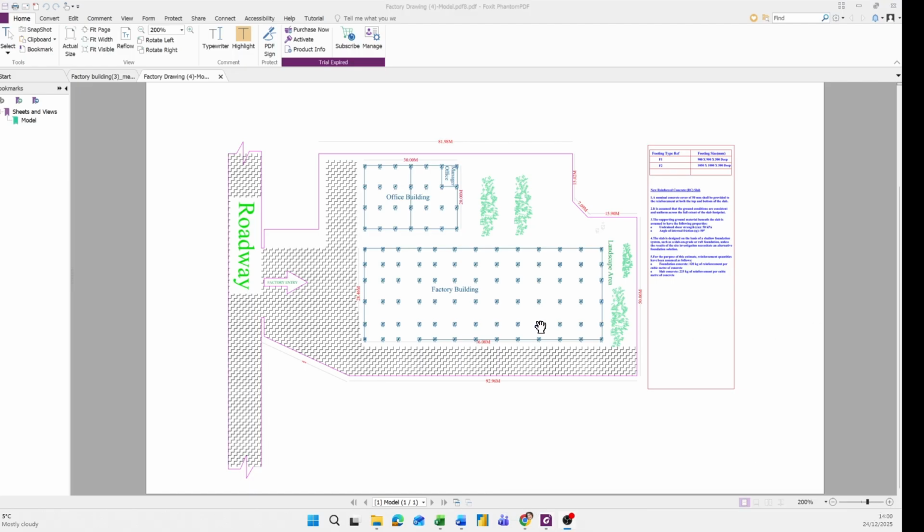Because this is a class 3 estimate, not all details are available, so we need to make some assumptions. For example, we may assume one main entrance gate, standard perimeter fencing around the site, signage, etc. These assumptions should be reasonable. It is very important to clearly state all assumptions in the estimate so everyone understands what is included and what is not.